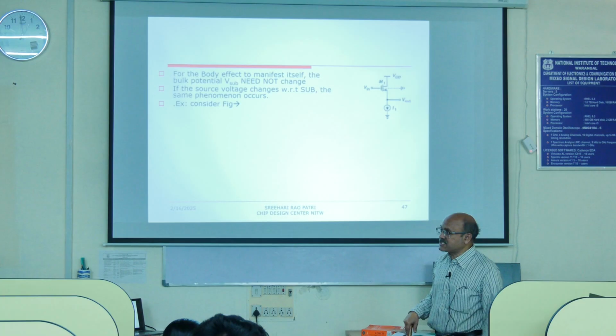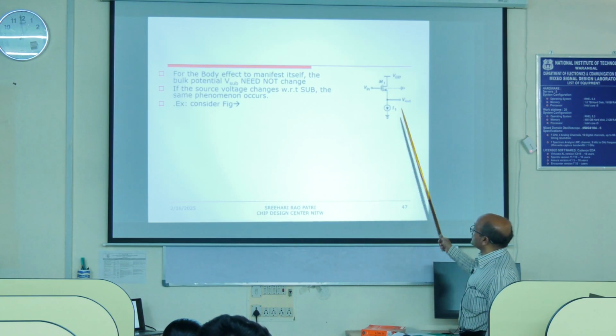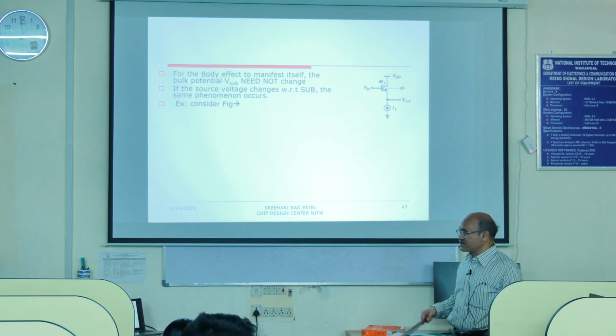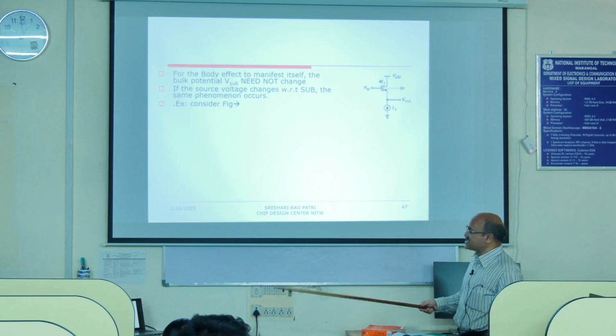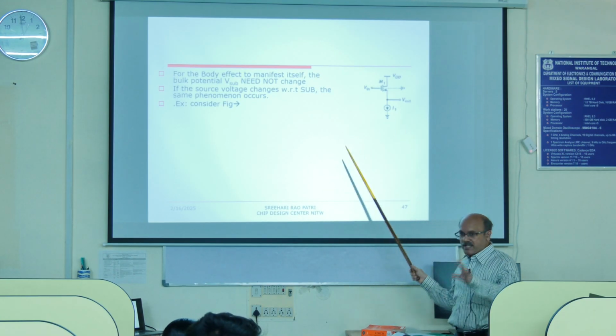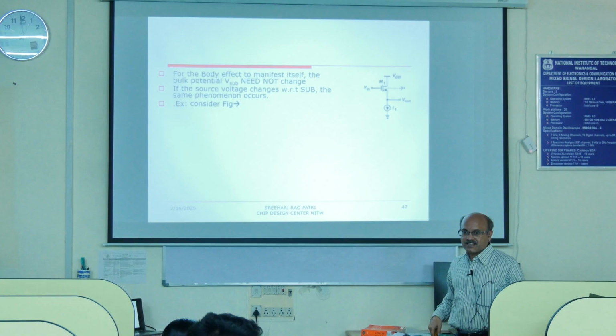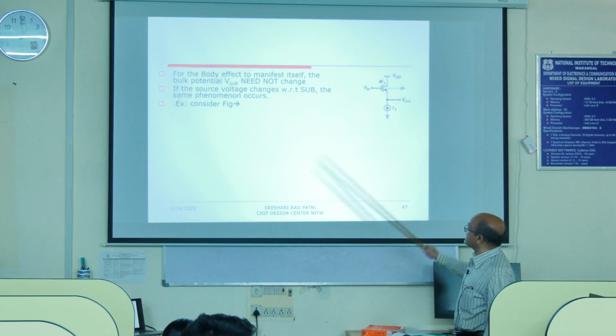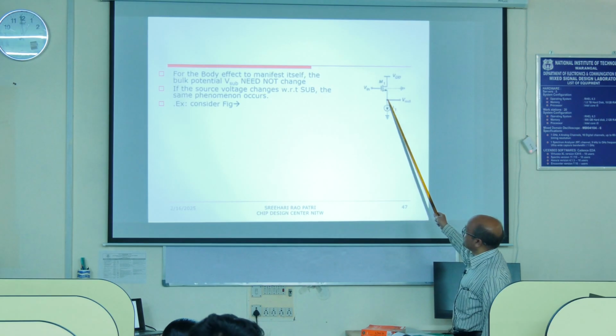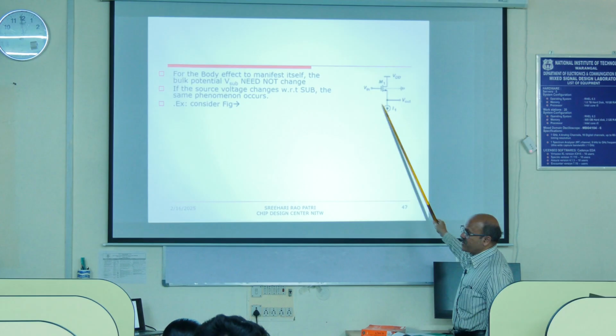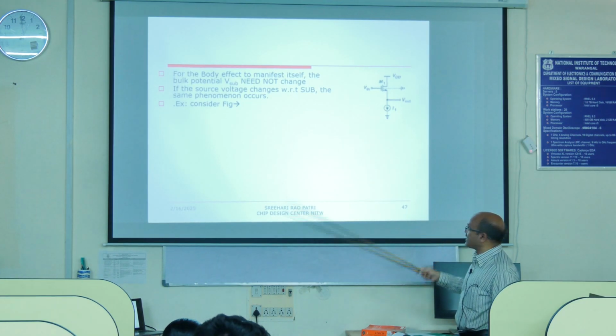Which implies that the circuit is wise, right? It follows the rules. You are increasing Vg, so now it will keep Vgs constant. It raises this potential. As input increases, it raises this potential, so that Vgs remains constant and therefore current remains constant.